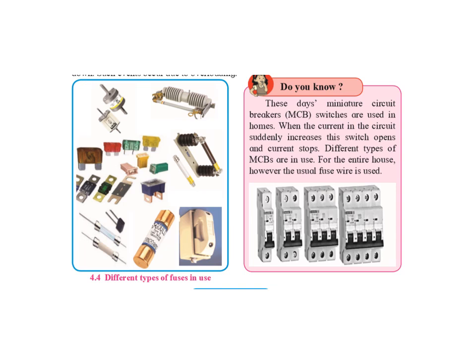That means the switch goes to the other side. It falls down actually. Instead of being on top, it falls down, and we say that it has tripped. And when it trips, only the geyser stops. No other electrical appliances get spoiled or hurt. That is the purpose of an MCB.